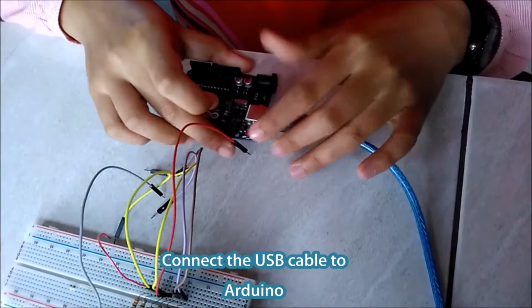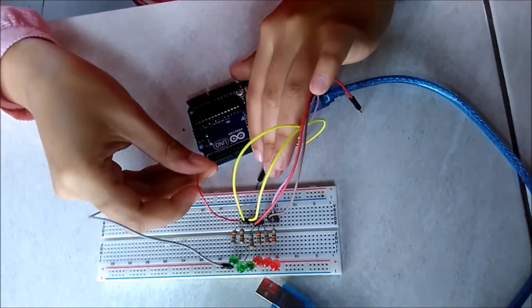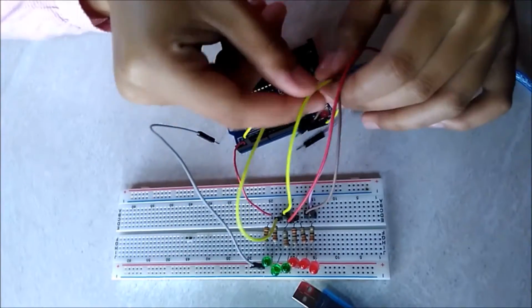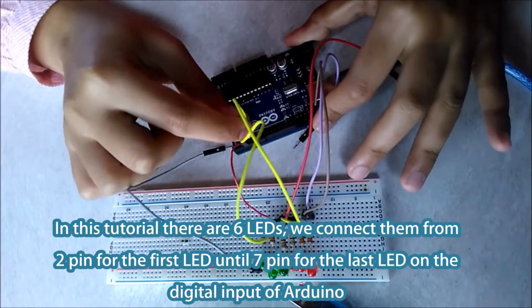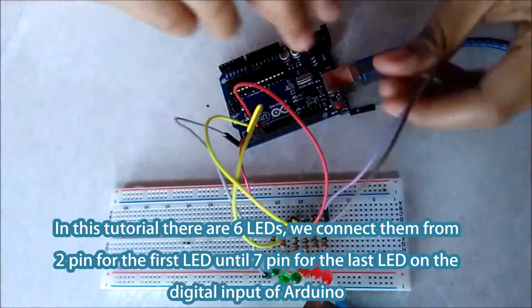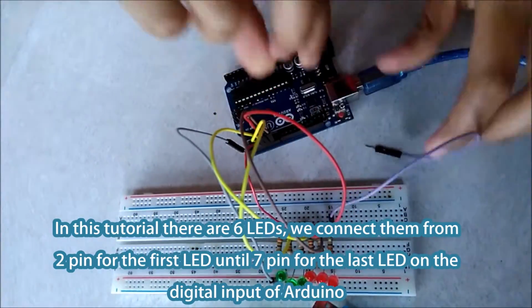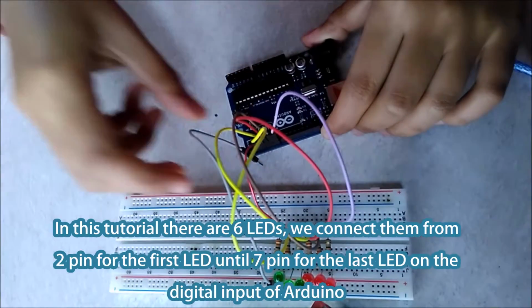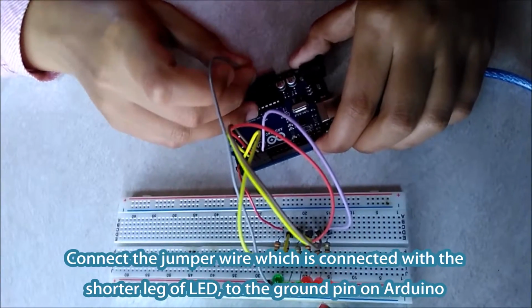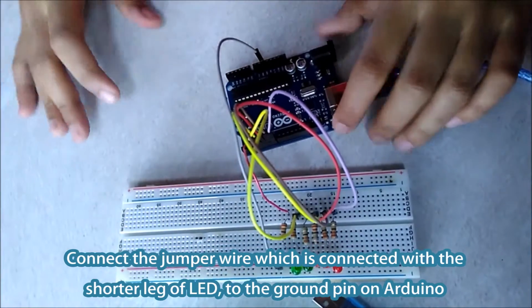Connect the USB cable to Arduino. Connect the LEDs to the digital pins of Arduino. In this tutorial, there are 6 LEDs. We connect them from pin 2 for the first LED until pin 7 for the last LED on the digital input of Arduino. Connect the jumper wire, which is connected with the shorter leg of the LED, to the ground pin on Arduino.